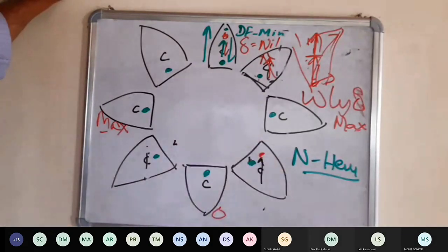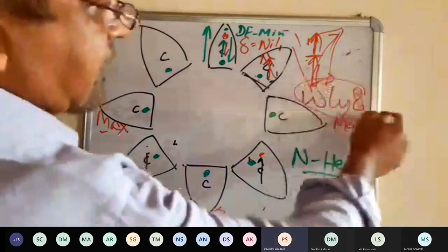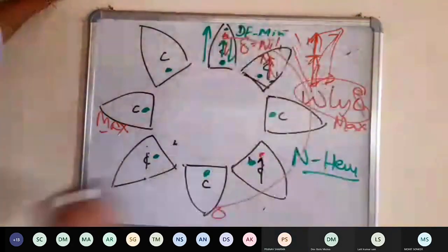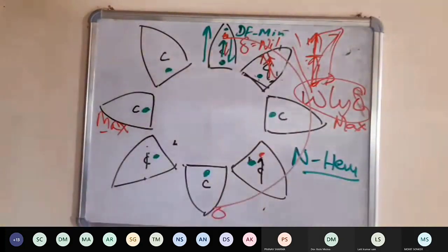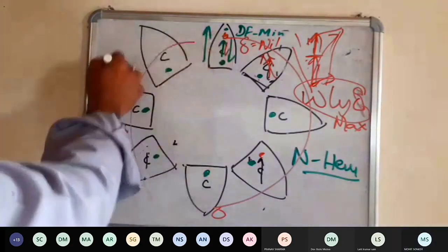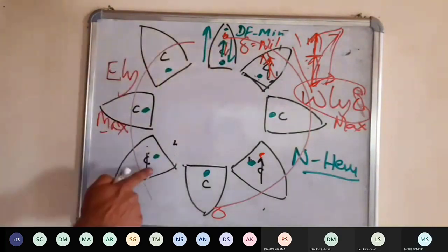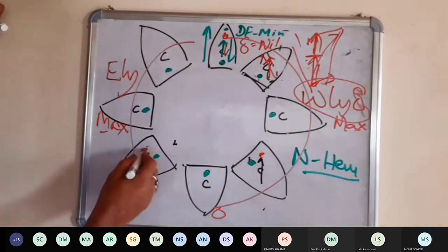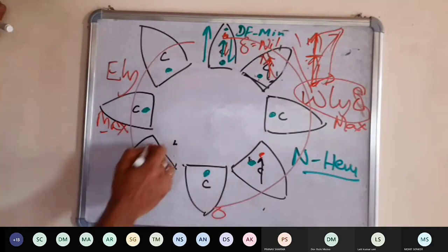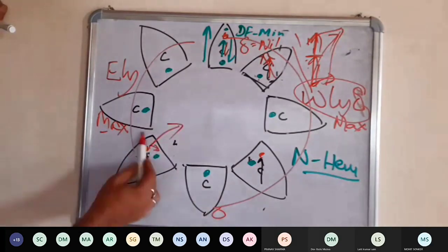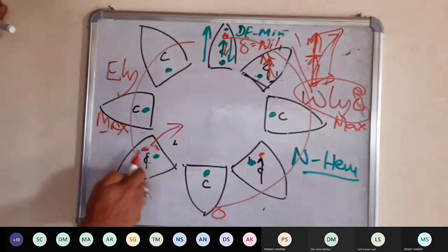So what is going to happen? Westerly deviation, we have already said westerly on all these courses, from 0 to maximum to 0. And easterly here, because if we have the red pole here, this is going to attract it and pull to this side. So easterly it will go. This will be attracted to this blue pole.